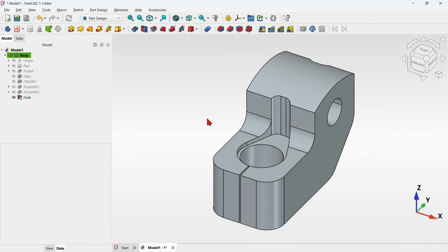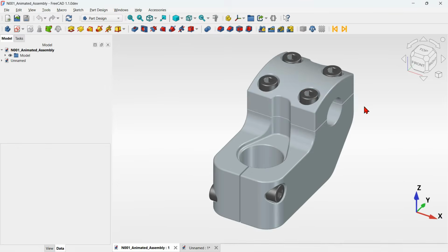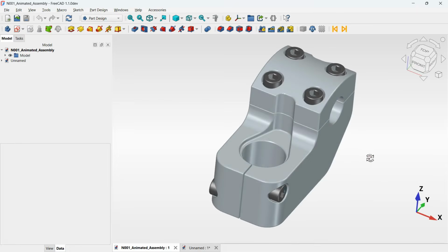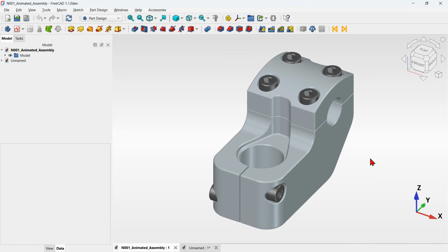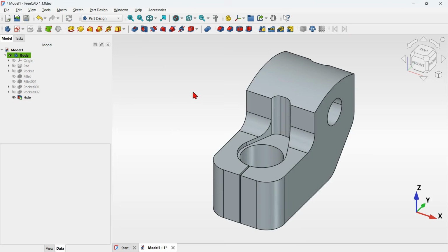The next thing that I think we can do is to create these 6 holes for the 3 objects in this 3D model. Okay, and to do that, it's very easy. We will use a combination of sketches and the hole tool. Let's go to our document, and first of all, let's create a sketch, attach it to the XY plane, and then we will apply an offset of 34 millimeters on the Z position of that sketch.